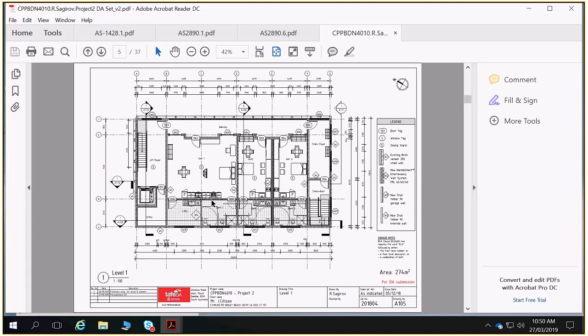The reason we need to be aware of the location of those columns is because we're likely to have wall load, so roof loads landing on top of this wall at, well, I can't determine at what spacings, but probably we'll have point loads over each of these columns, but then some form of support at either 600 centres or 1200 centres over that wall. That's what we can assume, but we can't know for sure.